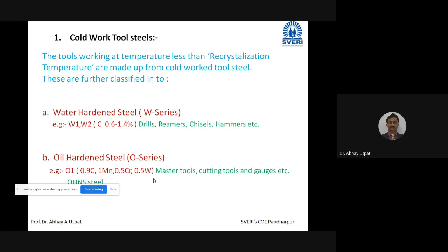So bainite and martensite are harder than perlite. If instead of forming the perlite phase at room temperature, we form martensite, then steel becomes harder. How to form martensite? Very fast cooling.